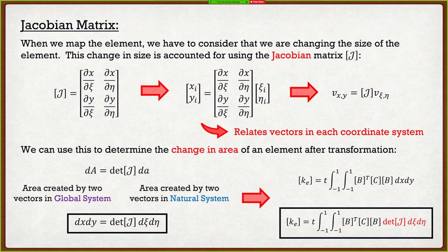So C actually isn't a function of x1 and x2. C was a function of the elastic modulus as well as the Poisson ratio. So C is not going to be impacted. C is going to remain C. It depends on if we select plane stress or plane strain. That's it. But you're right about B. We actually have some problems. So let's move on to our strains in our B matrix.